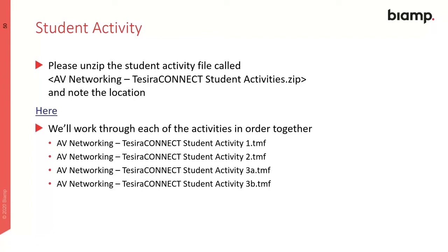And what's the next question? Can one TC5D be used over two Fortes and be part of both systems? Yes, indeed. You can make a TC5D part of bigger Tesira systems, whether it's two Fortes or 10 Fortes or two servers, it doesn't matter. All of our Tesira devices work with each other. There's no limitations there.